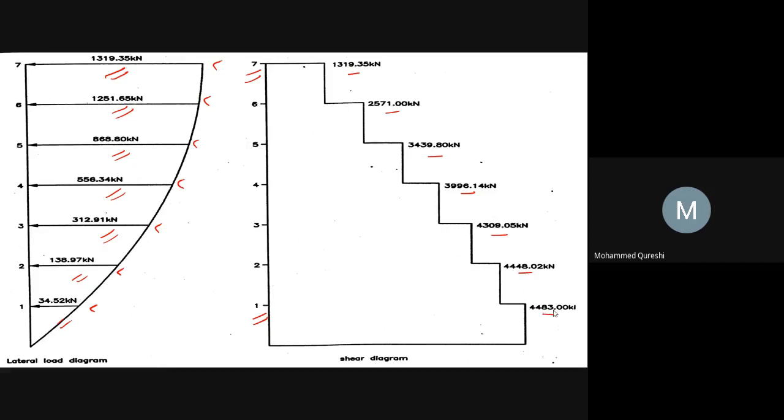In this way we have to find the base shear using the seismic coefficient method, and we have to draw the distribution of shear at each floor level by indicating all the values that we had obtained in the lateral load distribution with height table.